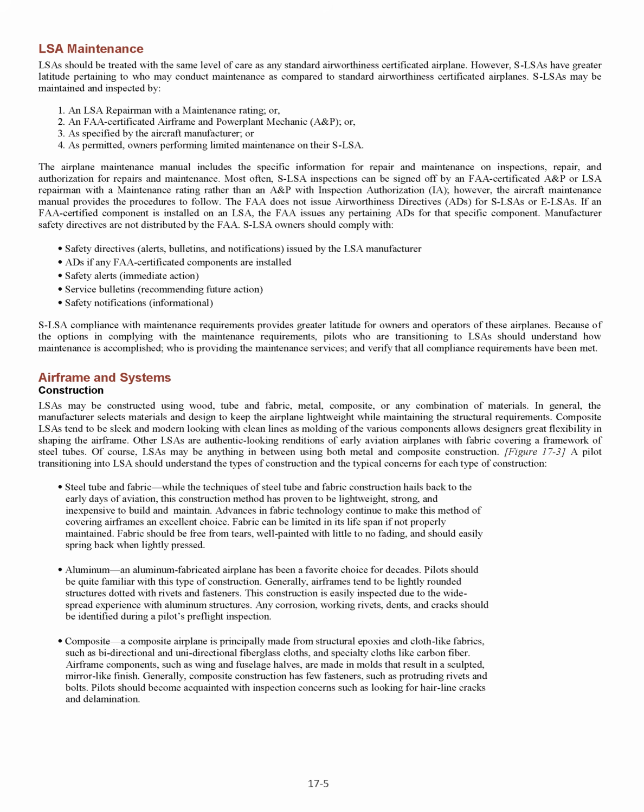The Airplane Maintenance Manual includes the specific information for inspections, repair, and maintenance, and authorization for repairs and maintenance. Most often, LSA inspections can be signed off by an FAA certificated A&P or LSA repairman with a maintenance rating rather than an A&P with inspection authorization, IA.